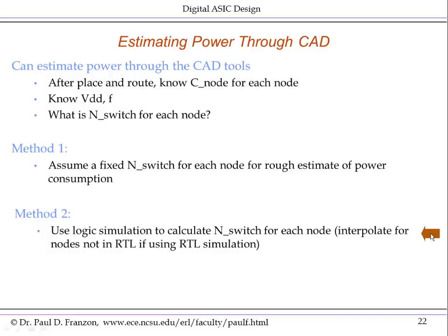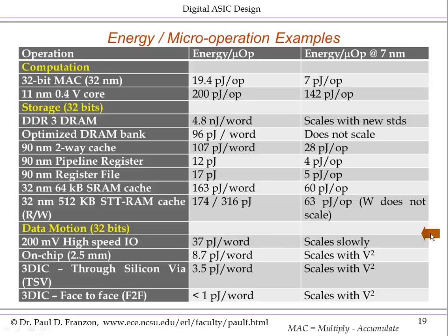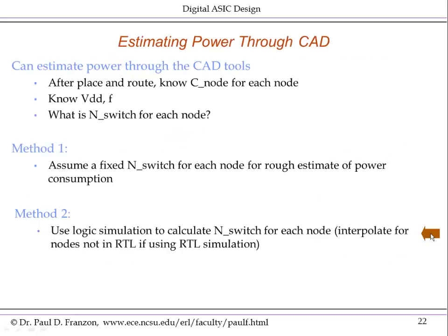So through these methods, you could actually directly calculate the power consumed in your design, and even play what-if games with the RTL in order to minimize the power. But again, good design defeats analysis. If you design thinking through a table like this, having it in front of you while you're doing design, then you'll be a lot better off than just trying to do it through simulation experiments. But nonetheless, this is very useful, and it's used in practice in order to understand and predict the power consumption of a design.